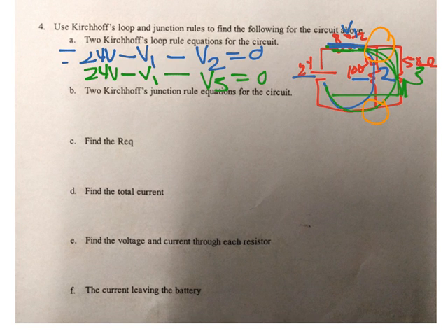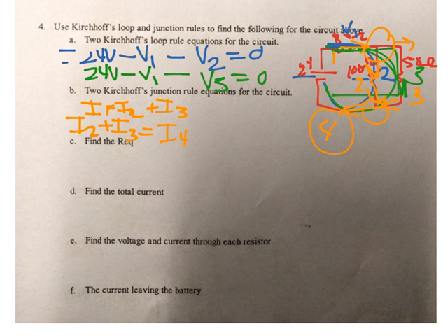Next we have two junctions. I'm still going to call this area 1, 2, 3, and 4. Going into this junction, current 1 goes in, and the ones that go out are 2 and 3. So together, currents 2 and 3 equal your original main current. You now have this section over here, 4. I just named it 4 because we're going in order. The currents that go into this junction are 2 and 3, so current 2 plus current 3 add up to make the total larger current 4.